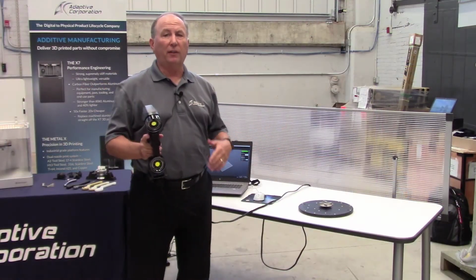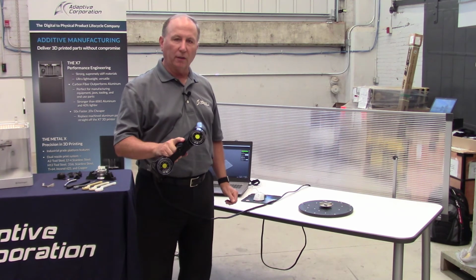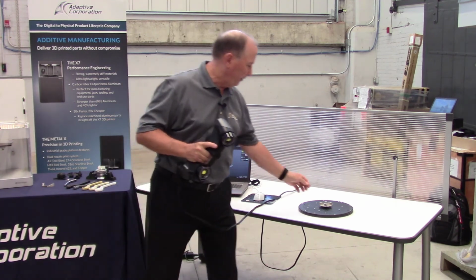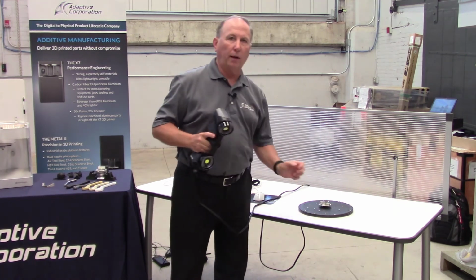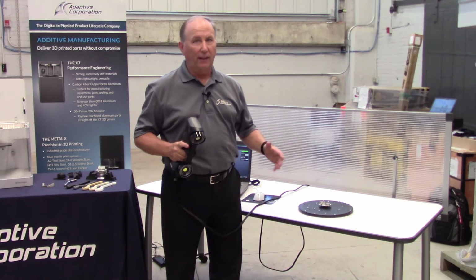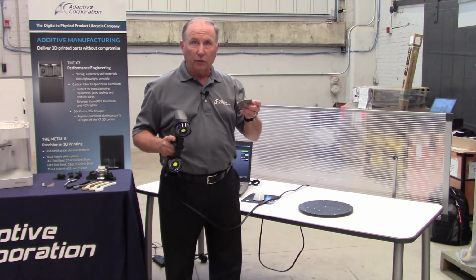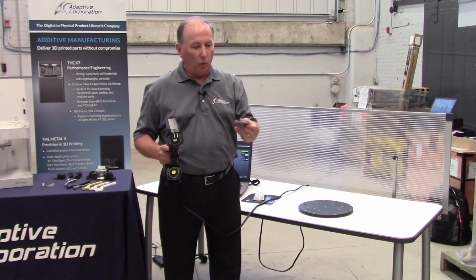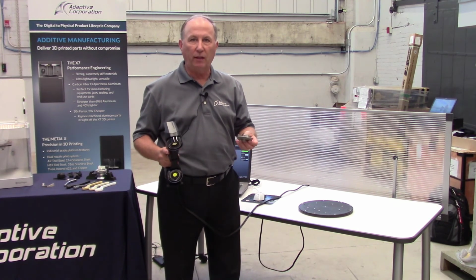The last step in the process is optional. It's a QA/QC process that we employ here in our lab, where we utilize 3D scanning to measure the parts. We can take the physical part, 3D scan it, and then in software we can call up the CAD version of this part. We can overlay the 3D scan of the part, and literally within a minute or two we can tell you if the part physically matches the CAD. So we got out of the sintering oven through the entire printing process exactly what we expected, or if the part is deviating a bit for whatever reason, where is it deviating and how much are we deviating?